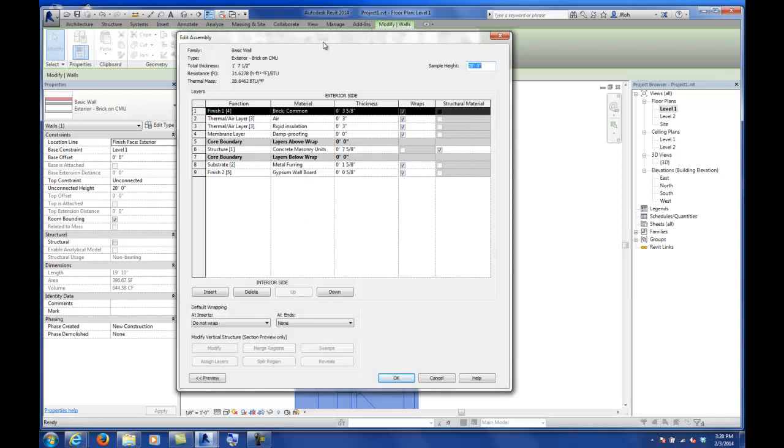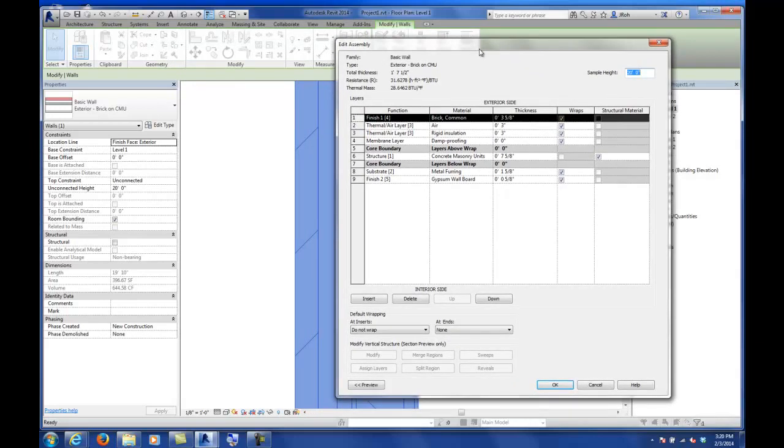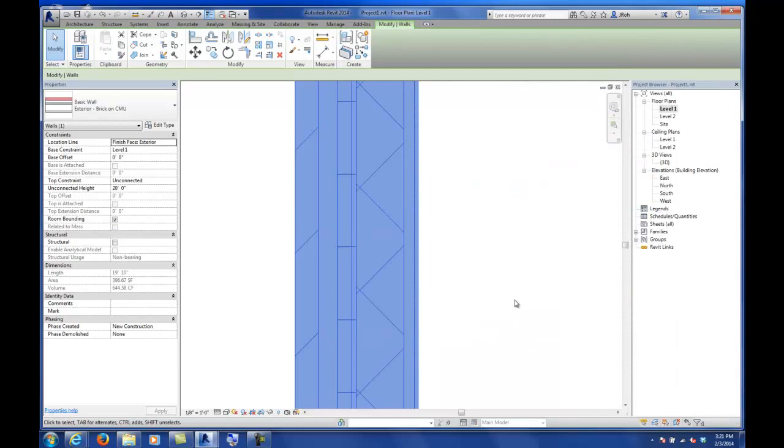This is what's called a compound wall in Revit. These are things where you would have to know more about your wall type, and you would eventually develop your wall later on in the semester. I think I'll get into more detail later on in the workshops, but just so you know, if you're drawing with these other wall types, you're going to have a lot more information already embedded that comes default with Revit. What I would recommend is that at the schematic level of design, you draw with your generic wall, and eventually we can come back to your generic wall.